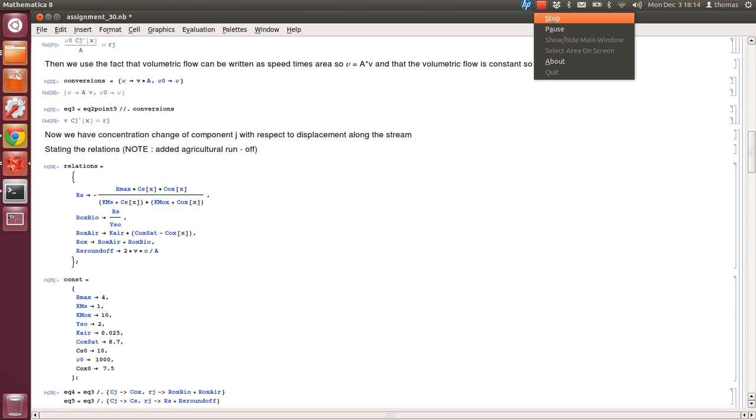So in my mix here, the concentration out is not just the concentration of the two things that are going in, meaning the flow of the river plus any additional flow, but it's actually dependent on the volumetric flow, and that is why I multiply by the volumetric flow here.